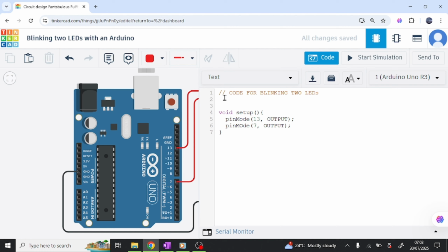So you don't need that top variable declaration. You do not need it if you are using the exact pin number here. But if you want to use a name, a variable, then you declare the variable, whether its data type is integer, float, double. You declare the variable and then you assign the pin to it. Are we seeing it now? So here we'll close what? Close setup.